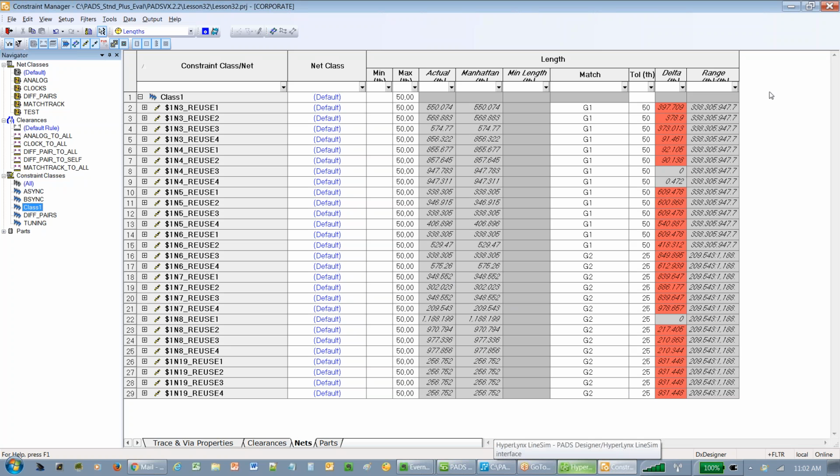So you can pull up your schematic after the tool has been worked on, or the layout has been worked on, and the placement's done, or the routing's been started. And I can go to the data field here, actuals, and say import actuals from the layout, and it will bring into the constraint manager environment you started from the schematic all the actual length information for you. Okay, so now I don't have to rely on talking to the PCB designer to see my length information, and the tool is even flagging if a net is violating a design rule that you created. Okay, and there's some help there as well.